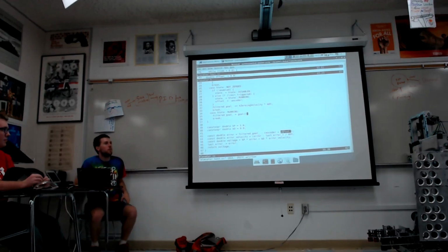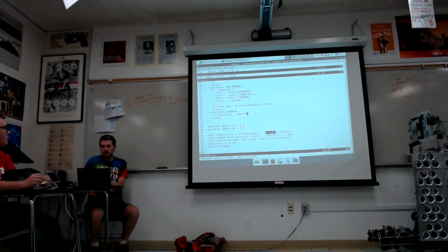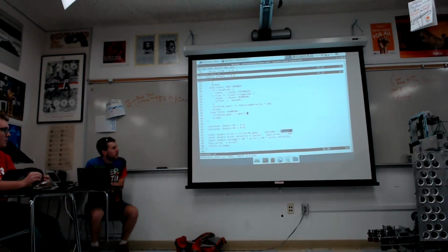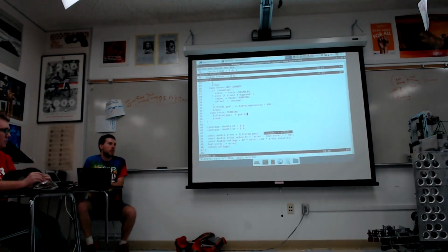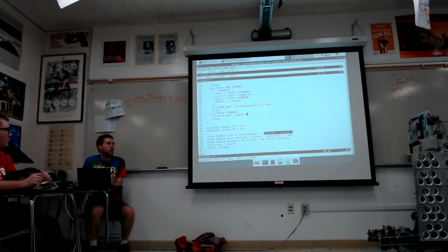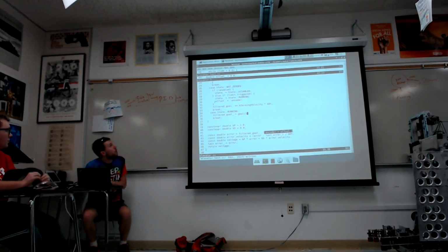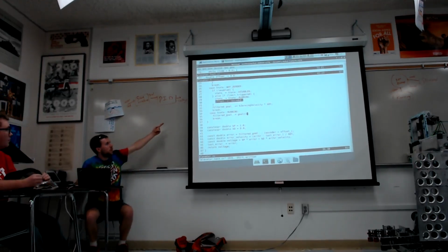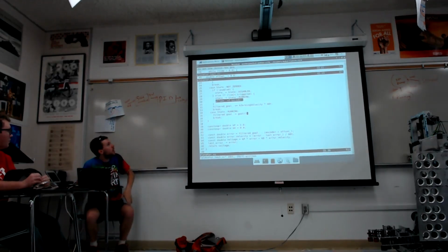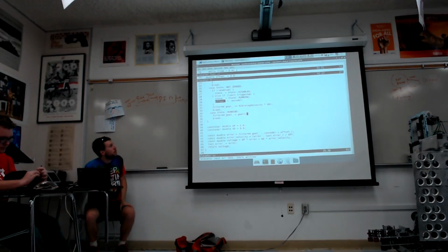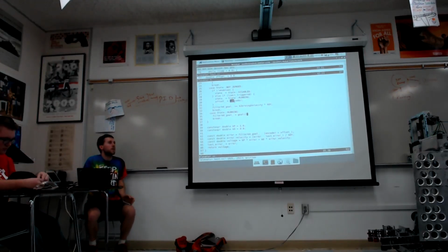So I'm creating a variable for that. The goal is this is relative to your starting point, and then this puts it in absolute coordinates. So this quantity here is now your absolute location of your elevator, calibrated. And then we need to figure out where that is. Lucky for us, we're going to define it so the edge is at 0. We could change this so the 0 is somewhere else. So that means we want our current position plus offset equal to 0 and we're calibrated, so we set it as minus 0.